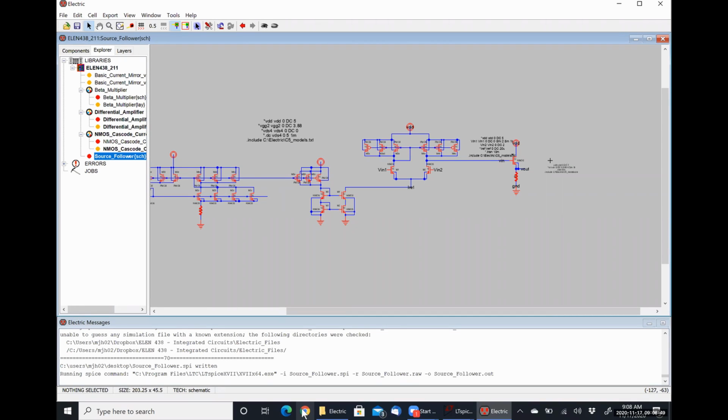But they only pull the Arduino off if I go from full speed one way to full speed the other way in a really short amount of time. Otherwise they work fine. So I only need it for those short bursts, which is why I was thinking about the capacitor. Okay, so you're thinking effectively temporary energy storage. Yeah, I'd give that a roll. Sweet. How quick of a time are you transitioning? Because that may require a large capacitor, which is going to be hard to do.